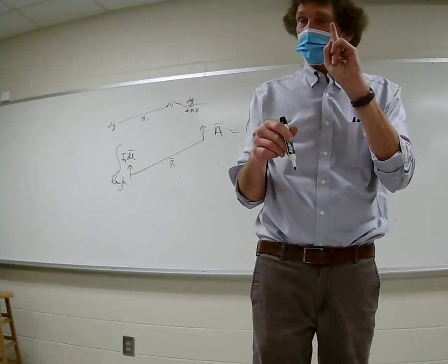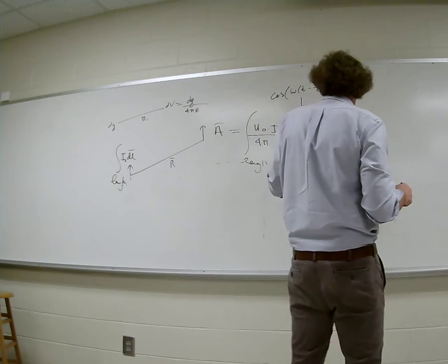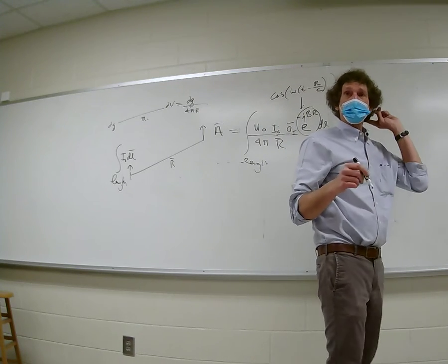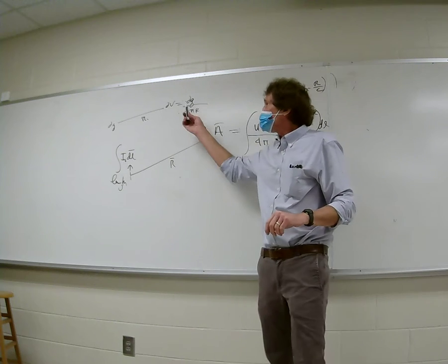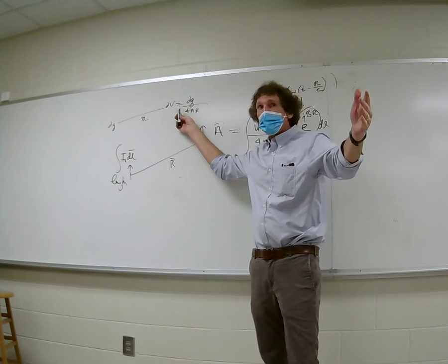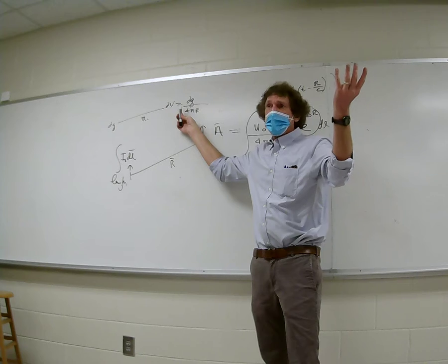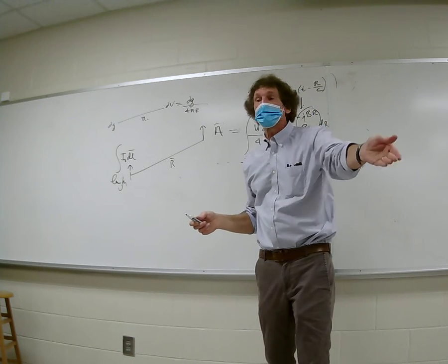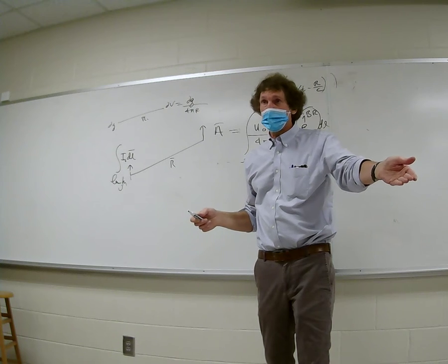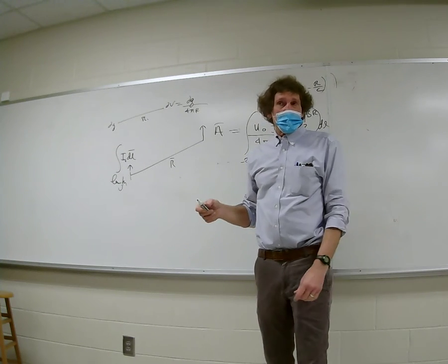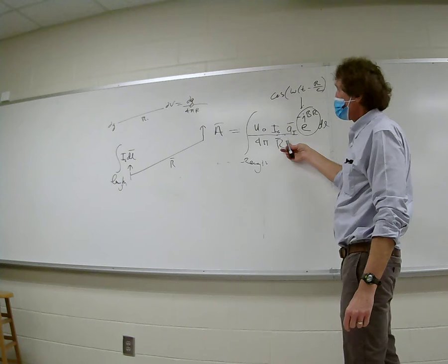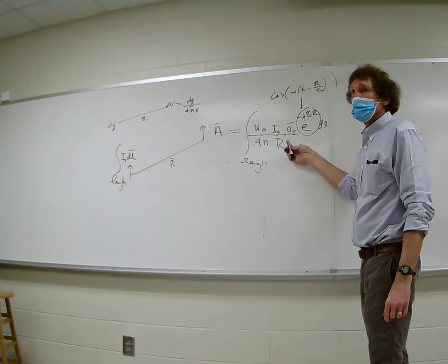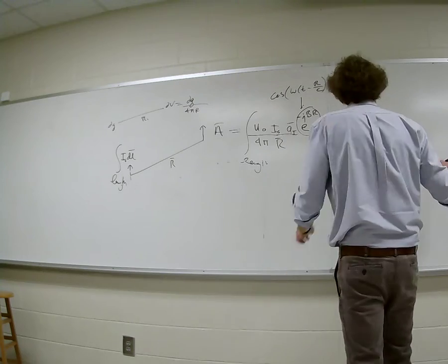Got that up, everyone? So I got this, so big deal. How do I get something of meaning that I can measure? You can't measure this. And by the way, you can only measure voltage when you have 2 points to measure it between. 100,000 volts means nothing unless it's with respect to something, usually a ground. You all follow me on that? Here, this you can't measure, no matter what. It's used as an intermediate potential to get something. And here's what you get.